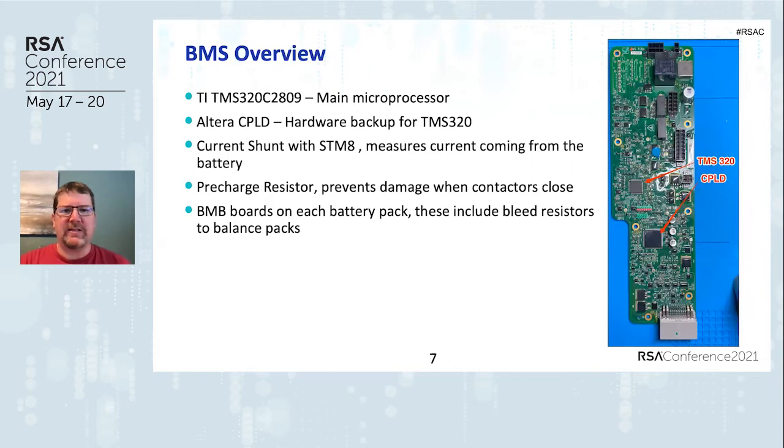So the battery management system itself, here's kind of a little hardware overview of the unit itself. It uses a TI TMS320 DSP that runs its own version of software. It's not Linux-based or anything else. It runs the TI code base. And then there's a backup to it, the CPLD, that also exists alongside the TI unit and acts as a more hardware backup. There's a current shunt.